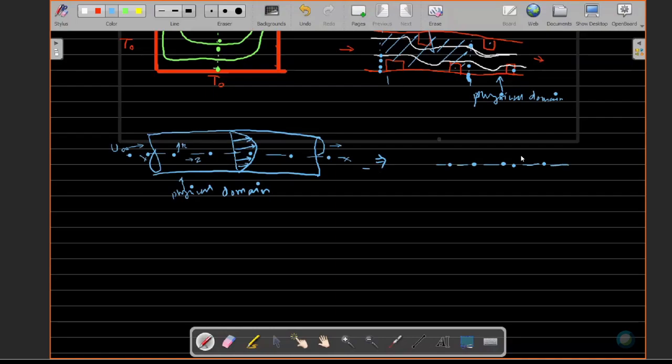So you can consider the top. These are the walls, so top wall, and this is inlet, and this is outlet. So one boundary condition here, another here, another here, and now you have reduced the domain by one half. Now this is the full domain, and the full domain is converted into one half, and you have to give suitable boundary conditions.